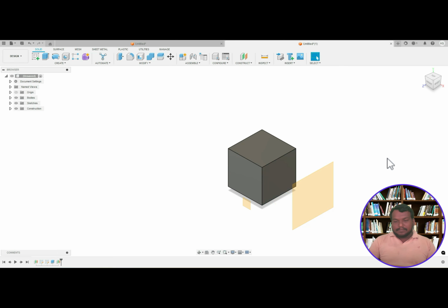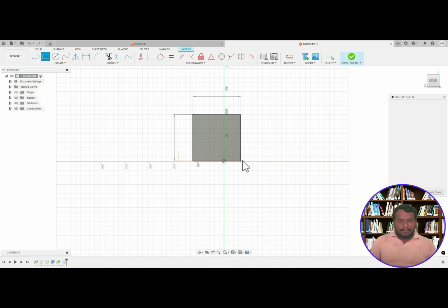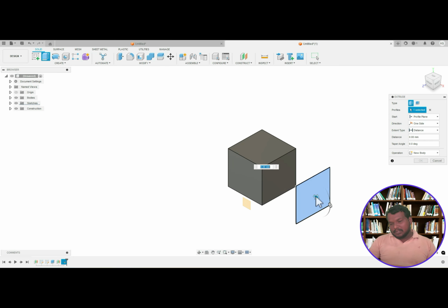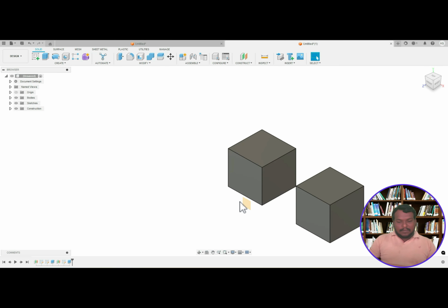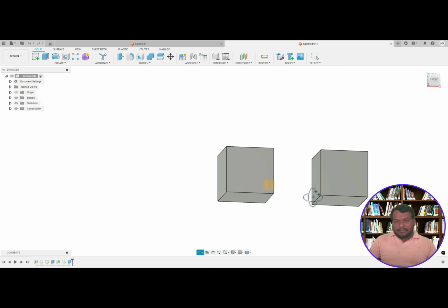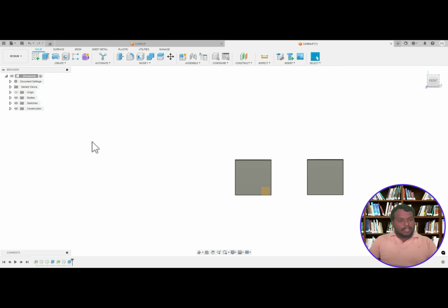Okay, next enter. Next go to 3D sketch and select the surface. Next draw 100 by 100 mm. Next finish sketch. Next extrude 100 mm. So we know the specific distance with our orbit and rotating toolbars. For this purpose we are creating the planes. Next, click on Escape.